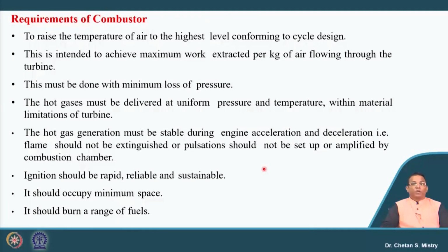The higher my turbine entry temperature, the higher the work extraction we will get, and we will see that this gives higher efficiency of my engine. So the higher temperature and higher work extraction need to be fulfilled by the combustor.